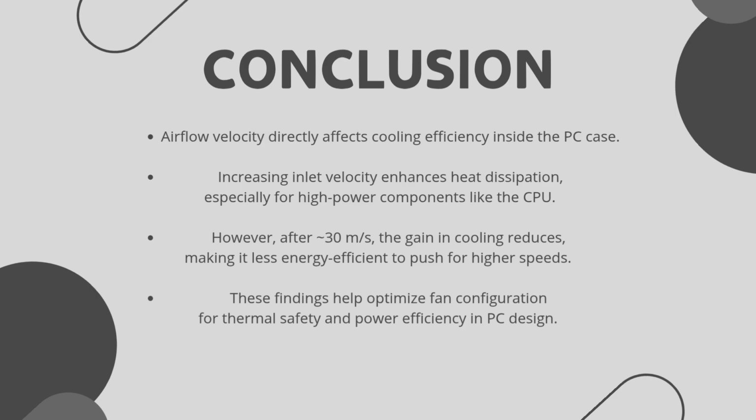Now, coming into our conclusion, the airflow velocity directly affects cooling efficiency inside the PC case, as we can see just now. Increasing the inlet velocity enhances heat dissipation, especially for high power components like the CPU.